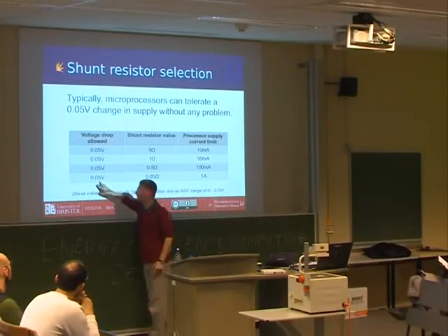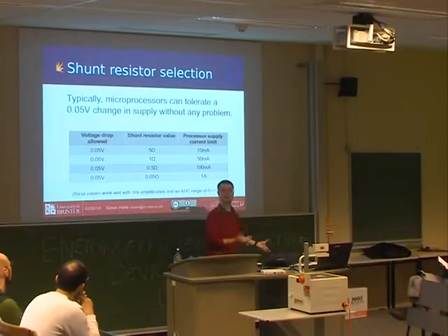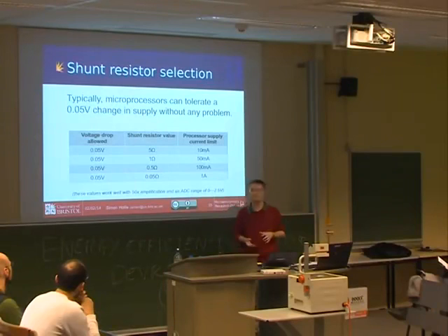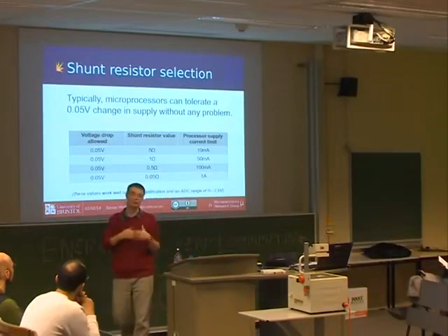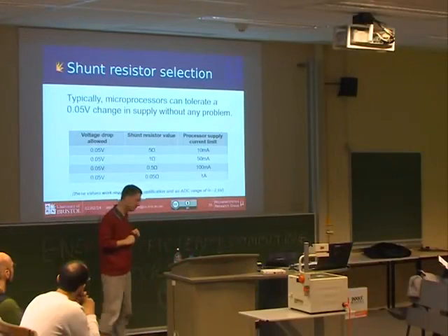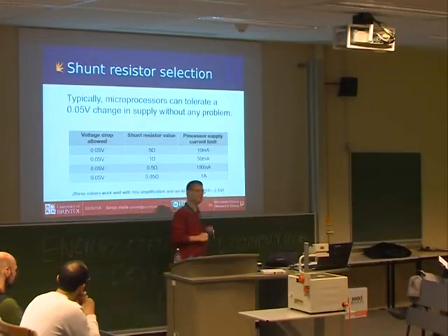So what you're now doing is feeding this kind of voltage into the ADC converter in a microprocessor, which has a range of 0 to 2.5 volts. So you're using some tiny, tiny part of that range. What you want to do is to maximize the part of the range that you use, so that gives you more resolution, more points inside the range that you can distribute.